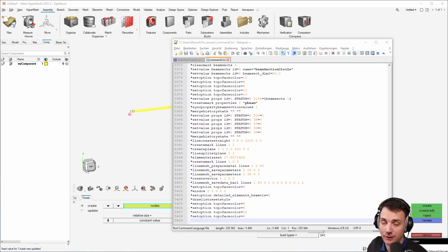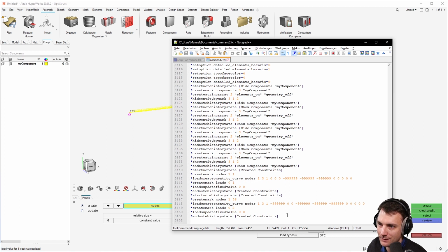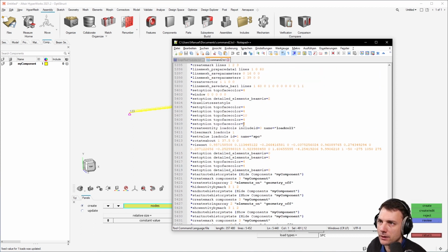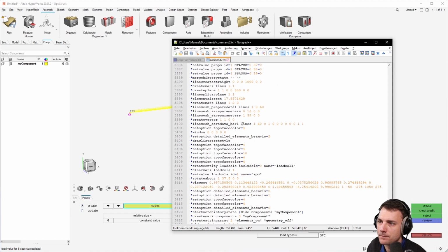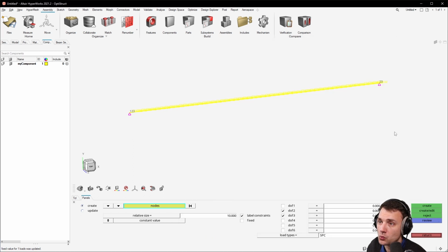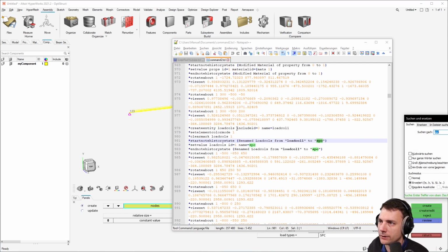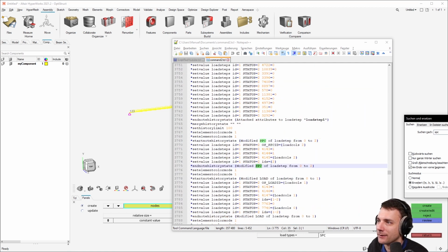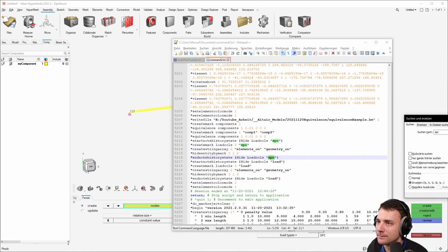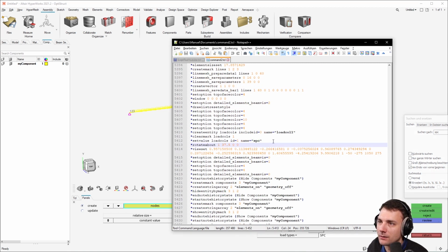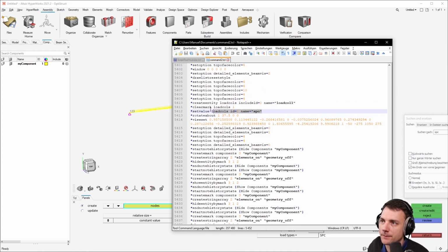Now the fun part begins, because how to select the nodes? If you have the ID, yeah, for sure, but if you don't have the ID, and we don't really, then it gets a little bit more complicated. So what we did here is the creation of the constraints. And where did we create... I have to see. Somewhere I should have created a load collector. Alright. Haha, I did it a bunch of times. This should be it, right? Yeah. So here we created a load collector.